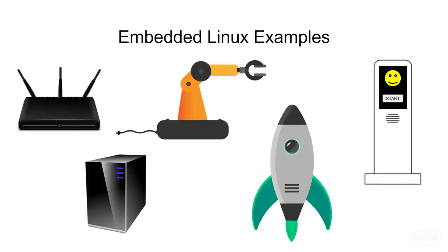Things like networking, databases, complex algorithms for something like computer vision, multiple processes, and so on dictate the need to use a full operating system like Linux over something like an RTOS or bare metal programming. In many of these applications, you'll often want a custom operating system in order to save on power and production costs. That means picking the hardware that best suits your needs and running a customized version of Linux that doesn't have all the overhead found in something like a common Raspberry Pi distribution.